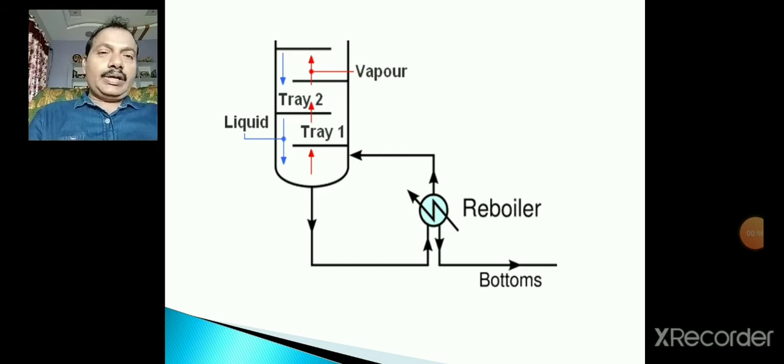You see how the fluid is used here to heat the reboiler, and the feeding crude oil is now descending from top to bottom in the blue lines. This is collected at different tap locations, and the vapor is moving upward.